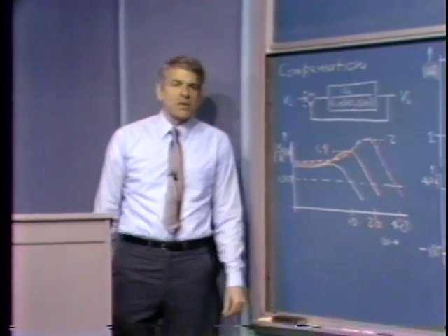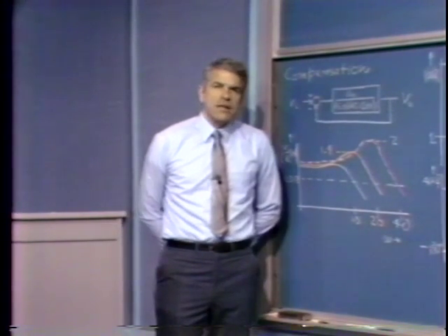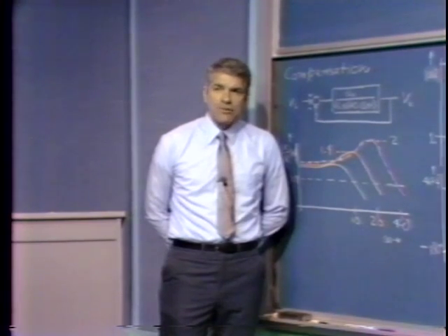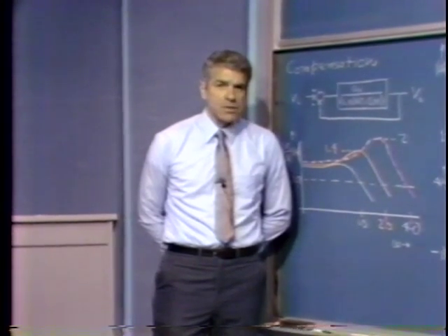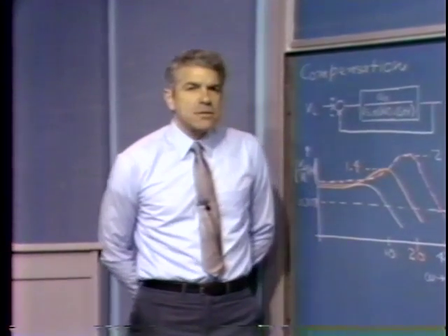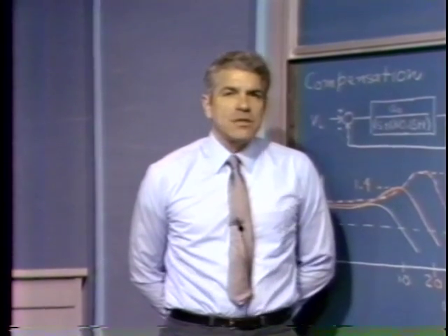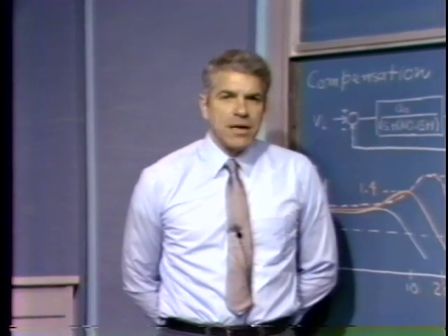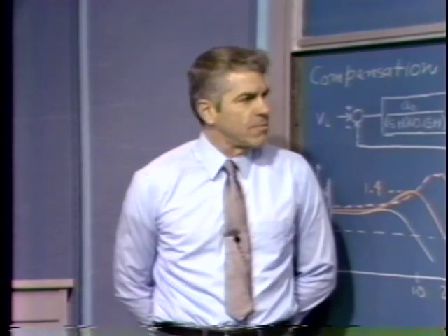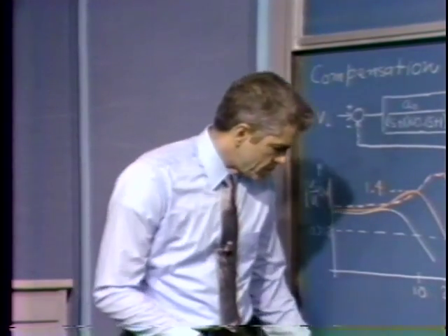Well, that sort of a construction is fairly easily done, although in reality we normally don't even have to do that much work in order to get a good indication of relative stability via frequency domain techniques. In particular, it happens that the closed loop response of the system is very nicely characterized by several parameters relating to the loop transmission, or the AF product. And I'd like to define those and then see how we use them.